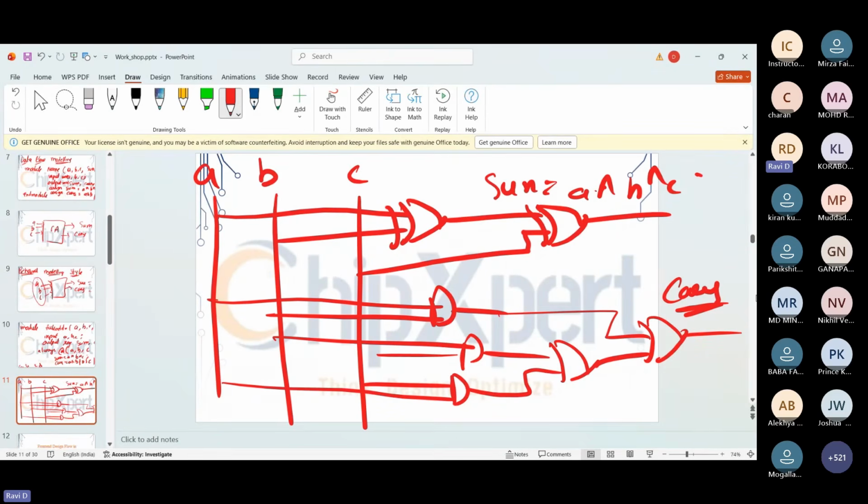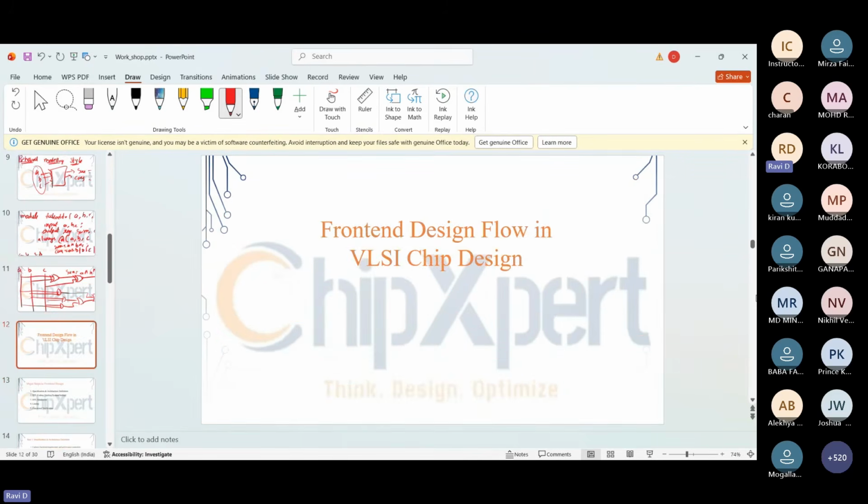In gate level modeling style, you are going to describe in gates, by calling the gates. In Verilog, we have a term called predefined primitives. That means we have some logic already predefined in our language. If we want to use that, we can call it with that name.